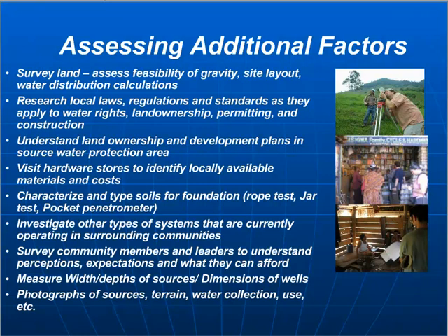But you should always plan on surveying the land early on to get a sense for what the elevations are of the source, a potential storage location, the highest house in the community, the lowest house in the community. Having too much of a difference between elevation can also be a problem. So you need to have a general understanding of the feasibility of a source based on the elevation of those features.